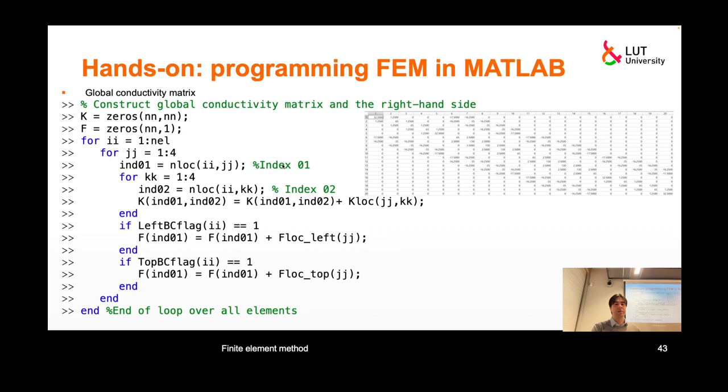Okay, so this was maybe a little bit not obvious part. You can check that it works correctly. And then we do approximately the same with the right-hand side, but a little bit simpler because we have just one vector and we just need to position in an appropriate way the vector of local contribution to this global right-hand side vector. So we are using only one of the loops. We don't need both of them because it's one-dimensional. So we use this JJ.